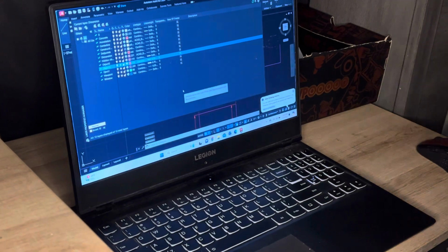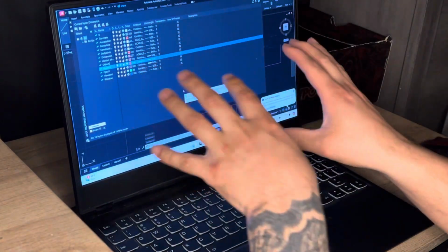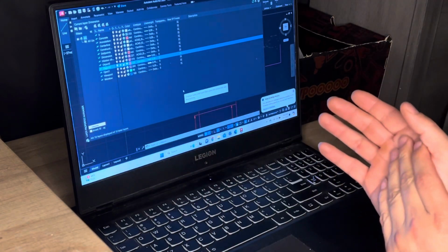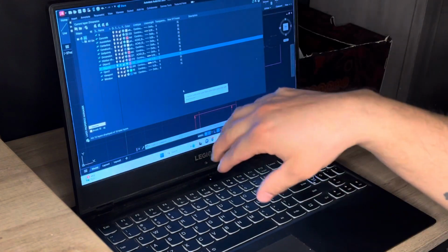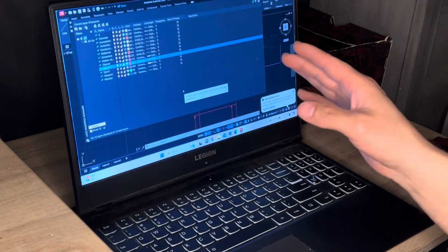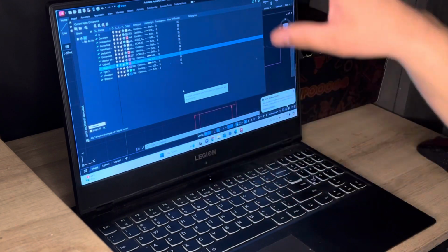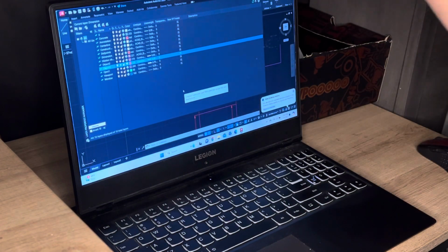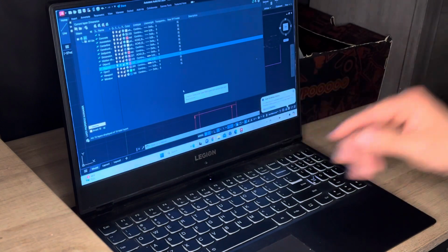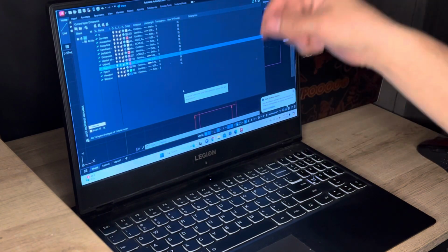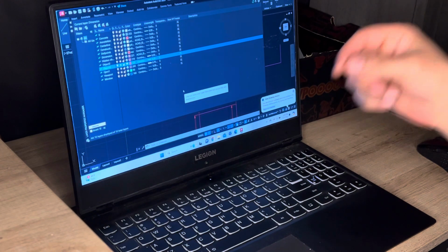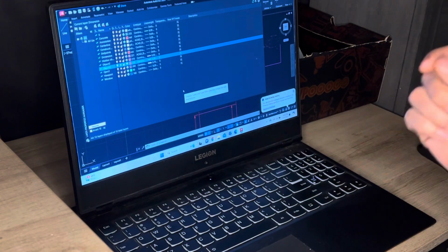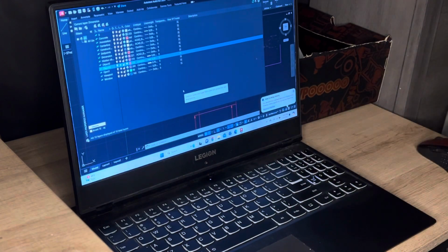And the reason that you would want those to be different thicknesses is so that when you print your drawings, they're going to print bolder or less bold, because you might have more important objects than other objects. So your perimeter or exterior walls might be object 1, and they're going to be thicker. And then your interior walls might be object 2. They're going to be a little bit thinner when they print, because exterior walls you might consider more important than interior walls, right? Same thing when I'm drawing components on a deck. Depending on what detail drawing it is, I might consider my beams more important than another part of my drawing, like a joist, right?